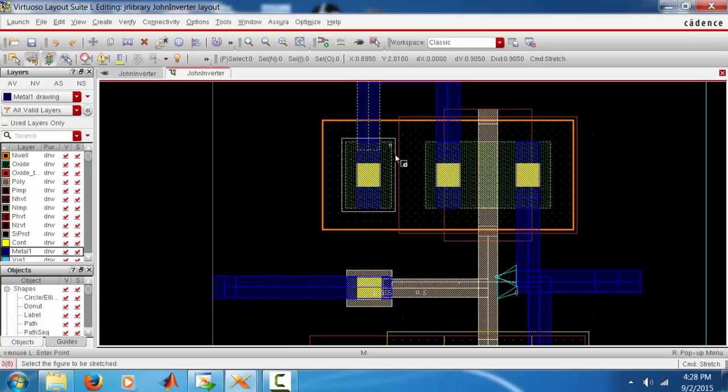The other is we need to increase the width. Since the MOSFETs have a minimum width, the default symbol which is created by Cadence is not, that is, the size of the implantation is not according to DRC. So we need to increase the size of the implantation. But if you press only Shift and F, it will not give access to the internal layers of the mask.